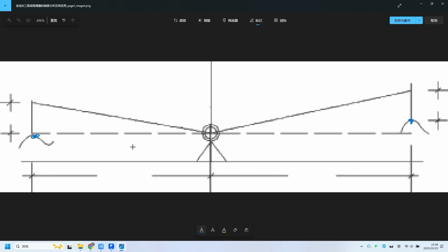When we observe, we also observe the position of our total station and the height difference with this point, assuming what height, and then the height difference with this point. In the triangular elevation line, we follow the direction of the line's movement. Usually, one of them is called forward view, and the other is called backward view. It actually means the same as pushing a plane line or leveling. One backward view and one forward view.